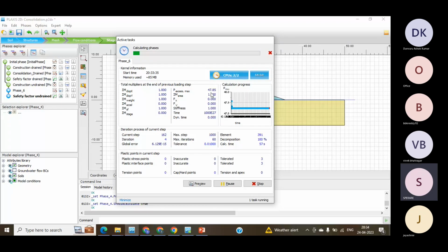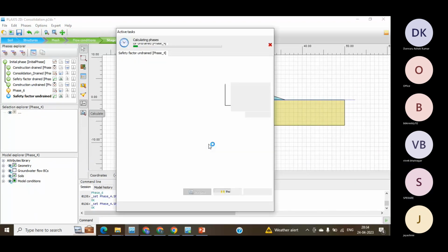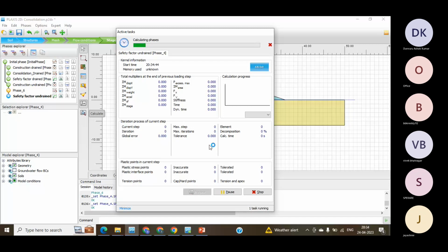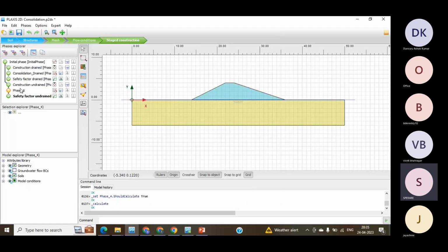this is where the pressure you can see here is like 47, and it could not solve this. And you can look at this particular calculation too. Again, the number of steps is not sufficient here. So you can see the behavior you have seen by selecting drained conditions and undrained A conditions. Why are you facing so many problems when considering undrained A conditions? It's always going to consider the excess pore pressure conditions.